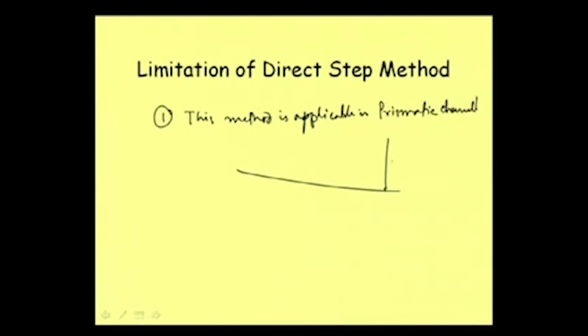First, I must say that this method is applicable in prismatic channel only. Why? Well, this is one limitation of this method. The reason is that, say, y1 is known, we are calculating y2.